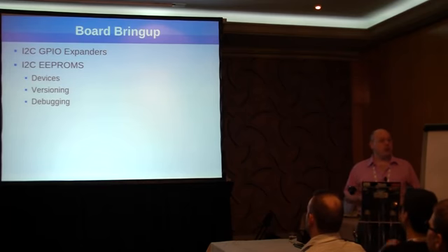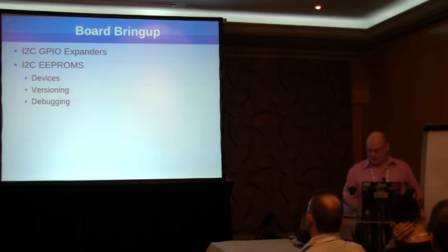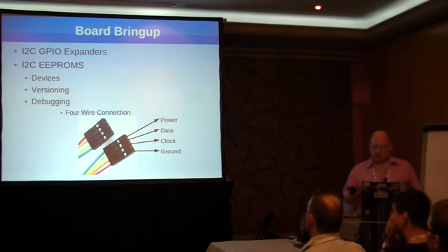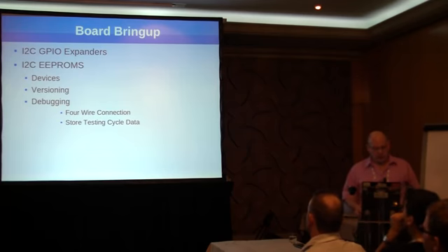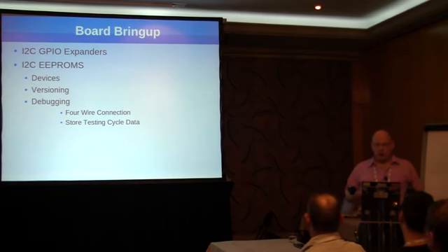So, what can we do with EEPROMs for debugging? It's read and write material, but there are a lot of things that you can do with it. Just like the I2C GPIO Expander, all you need is 4 wires: power, data, clock, and ground. So, when I get a new design that I need to test, I want to do automated cycle testing. I'll set up the board to boot up, do a series of tests, and reboot. And I may set up 6 or 7 of the boards all together and leave them running over the entire weekend. So what happens when the board fails?